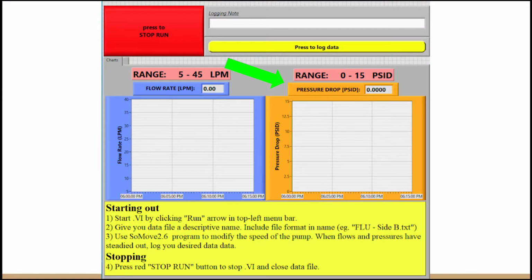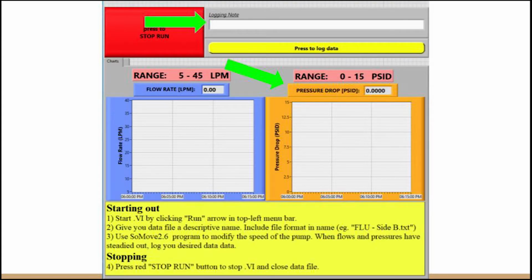Once the computer controls are on and ready, check and record the pressure differential reading for a possible offset. The system is now ready for data collection. On the input line in LabVIEW, enter the flow rate, motor frequency, and pipe description. Click record and stop after approximately 20 seconds. This will be done for a number of different pipes, with each being tested over different flow regimes.